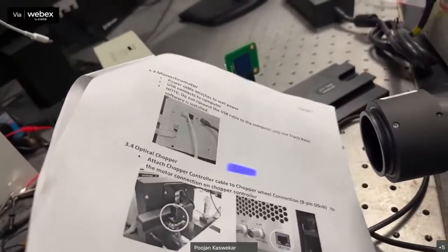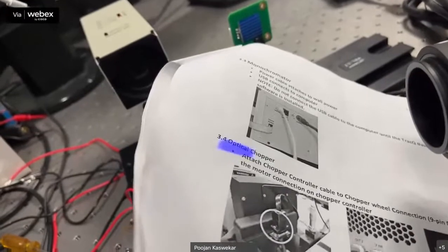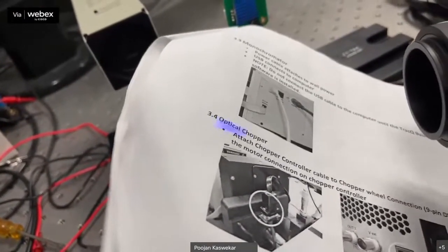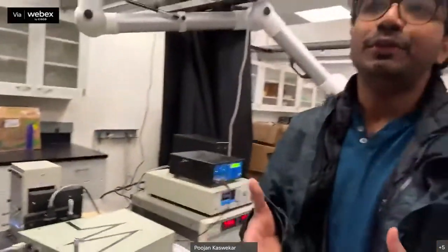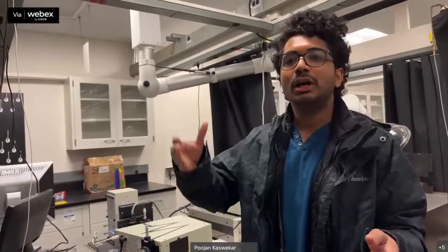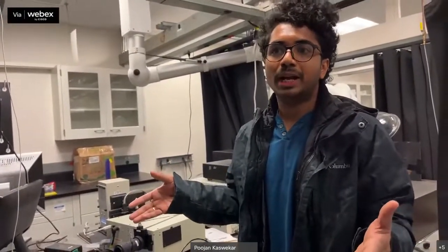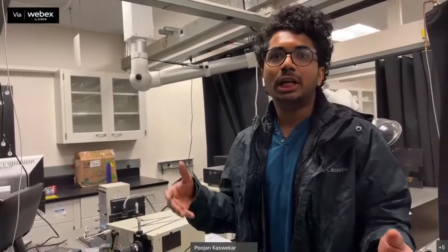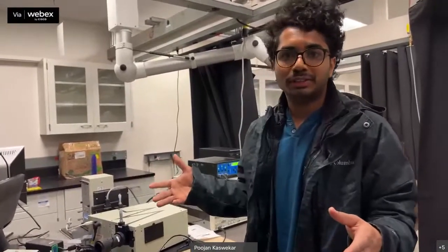This typical instrument can scan from 300 to 1100 nanometer wavelength. So it will show you how your device is performing at each wavelength. Suppose at 400 nanometer, how many photons you are absorbing, for 500 nanometer, how many photons you are absorbing. If you take a device with 1.51 electron volts, you typically assume it will absorb all the photons until 770 or 780 nanometer. If it is a 1.51 band gap, 1240 divided by 1.51 will give you your wavelength of absorption. So you typically assume it will absorb all up to 770.